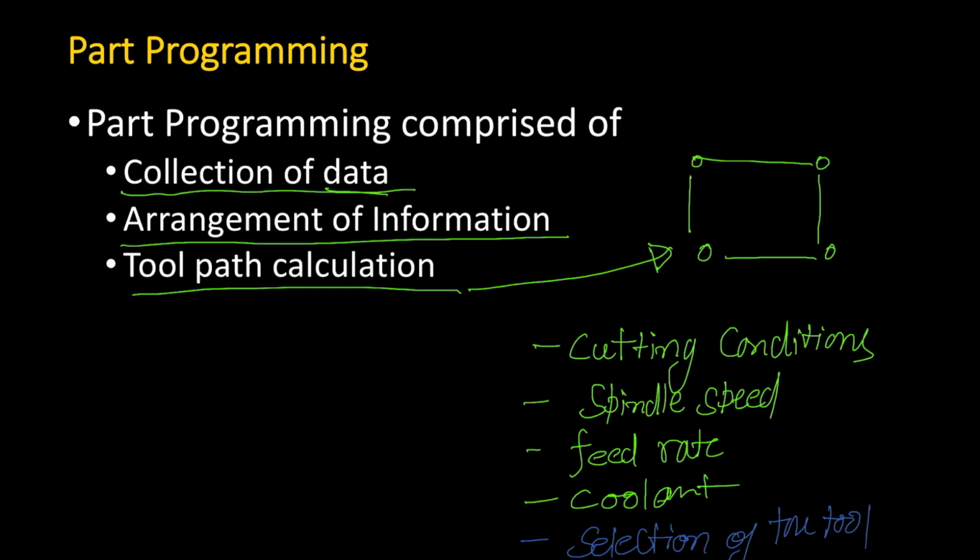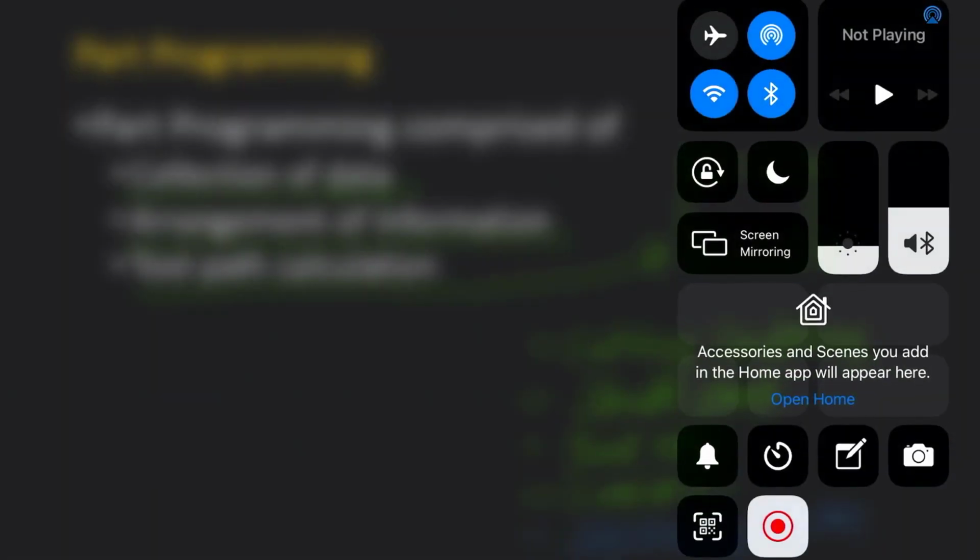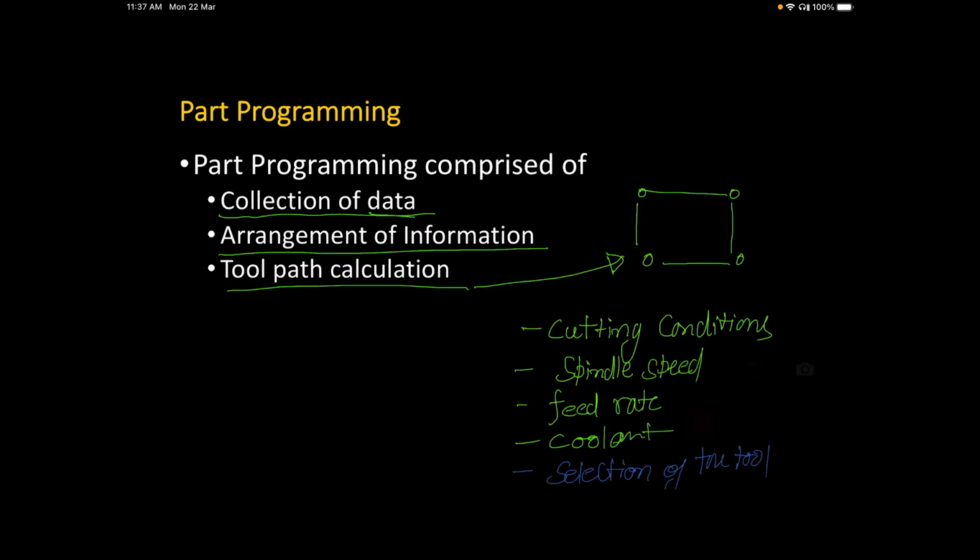Now the next step is to select the tool and determine the tool offset. You have to select the tool. We have to decide these things. We have to prepare for the part programming by selecting the appropriate tool and the tool offset, setting up the zero position for the workpiece, and selecting the speed and rotation of the spindle. Let us further discuss in detail.